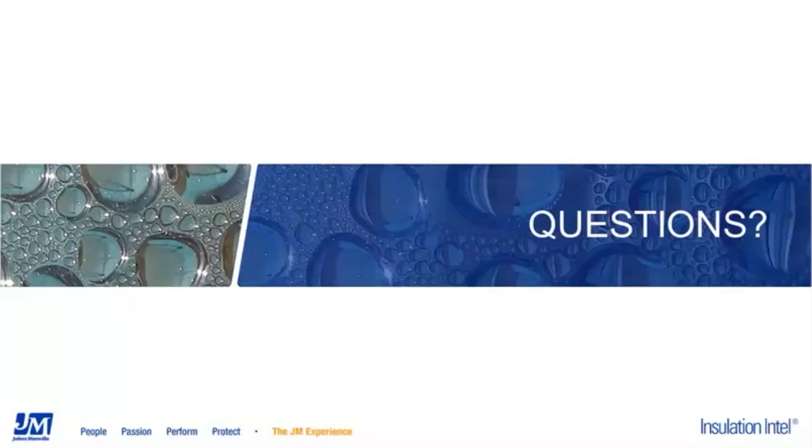If this was colder, and I certainly would think that could be possible, we would probably suggest that you refer to our refrigeration installation guides for Styrofoam and Trymer. There's a few more details that are required in refrigeration applications because they're colder than for chilled water. But the key thing is continuous vapor retarder, high quality insulation, proper jacketing.